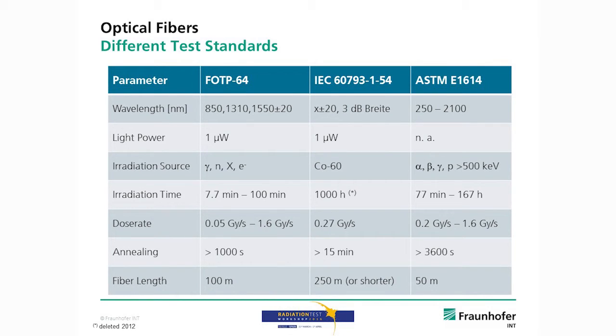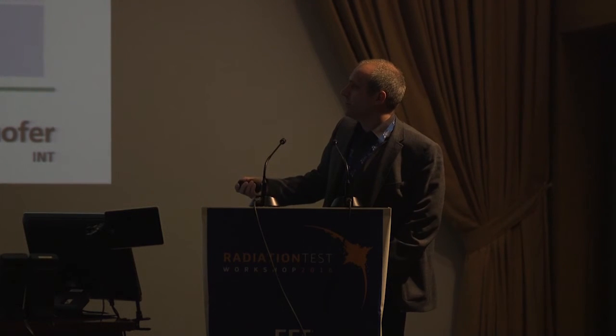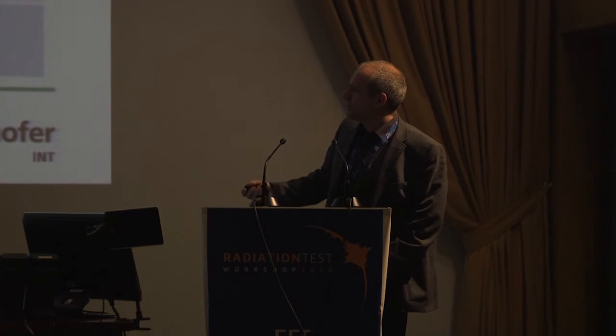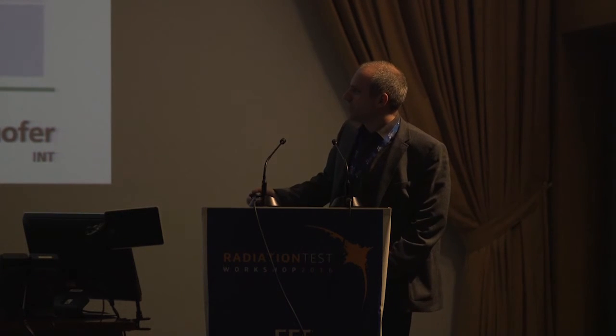And they also give you the fiber lengths before, which is a problem, because irradiation time and dose rate depend on your dose, and this gives you only one dose here, and so it really depends what kind of doses you want. If you're in a high dose environment, you have to go to an accelerated test with high dose rates. This is a little bit short for annealing because you miss some effects.